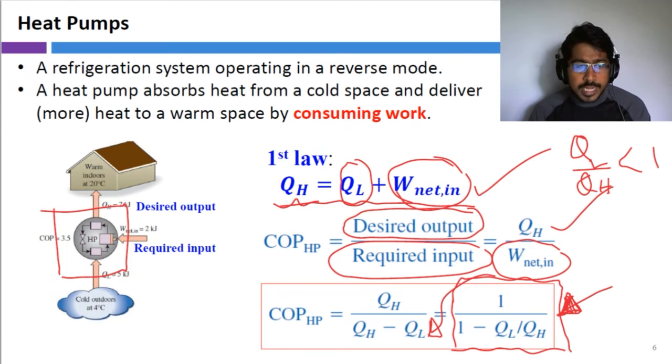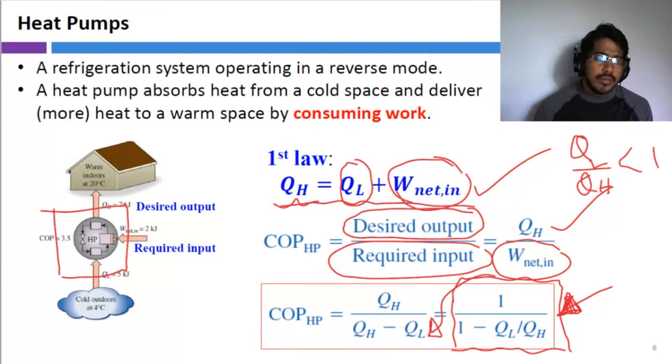But in heat pumps, it's different. If you add 1 kilojoule of work, then it will output 2 kilojoules of heat or more, something like that, right? COP is always greater than 1, right? So that's why people say that electric heat pumps are ridiculously efficient, or rather, that they are way more effective than furnaces.